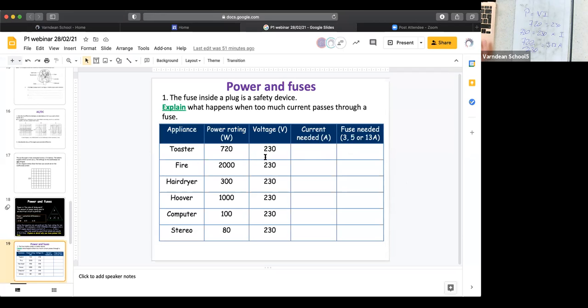Normal functioning of that toaster requires 3.1 amps. So the 3 amp fuse will blow the second you turn it on, every single time. But if 5 amps tries to flow through the toaster, which is too much, but not so much that your toaster is going to burst into flames, then it will fuse. And there's a problem if that happens, because that isn't the normal expectation.